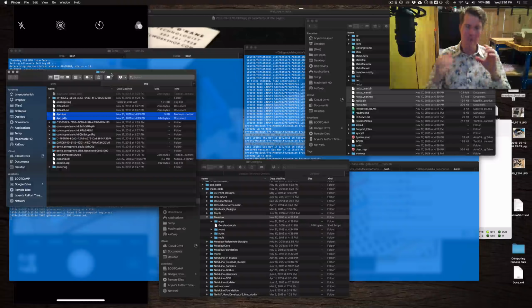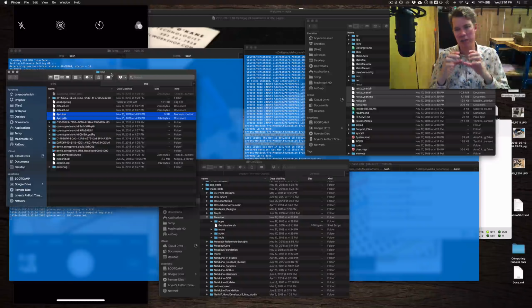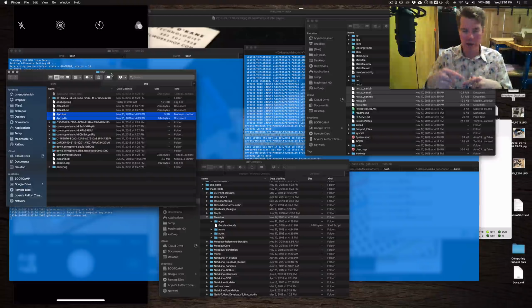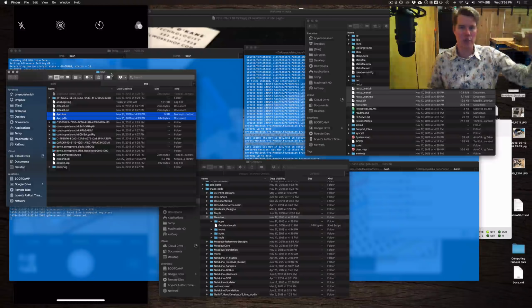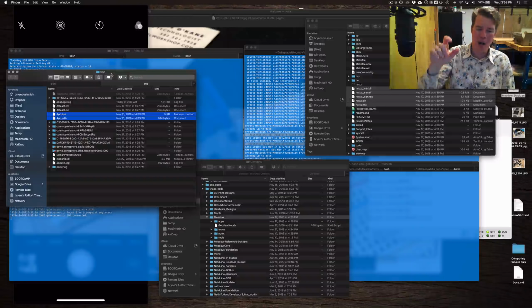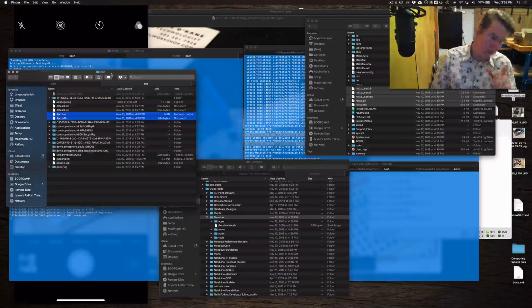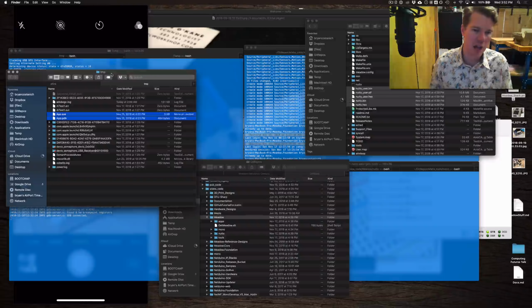And then we've got two ways we can execute an application today. We can bundle everything up into the OS package, flash it to the chip, and run it from there. What we do is execute the application from the flash memory on the board, which means instead of loading it into memory, the flash chip actually acts as memory. And then we have our additional RAM for a heap and whatnot. But that takes a little while, because we have to bundle this whole package up, flash it, and then run it that way.